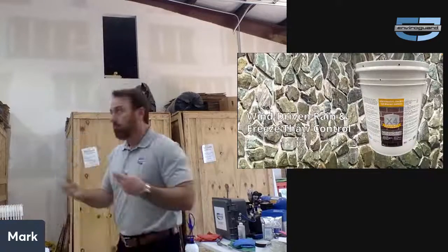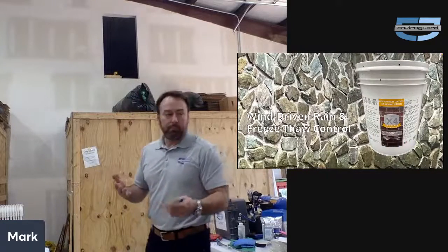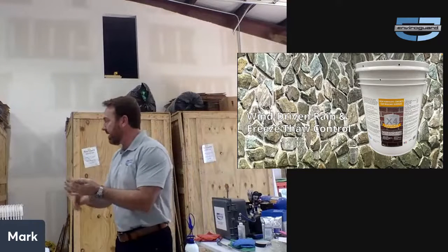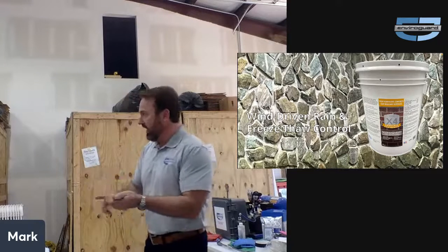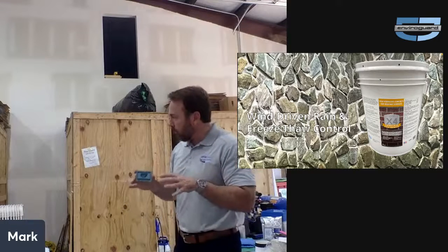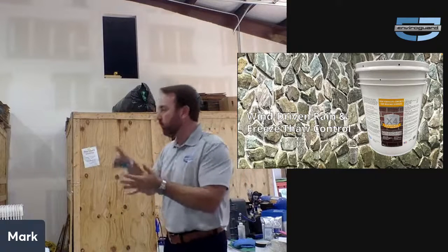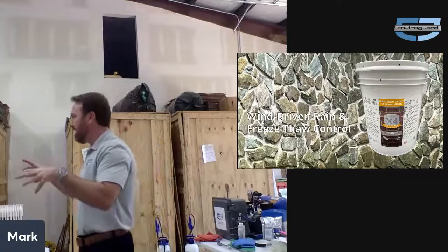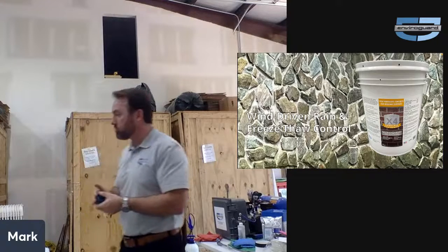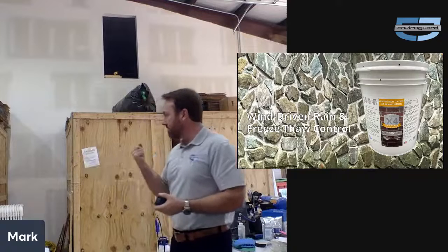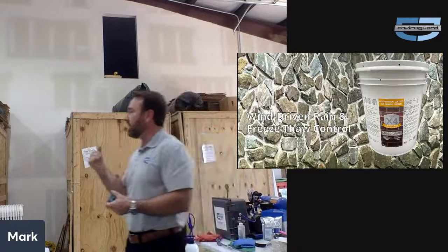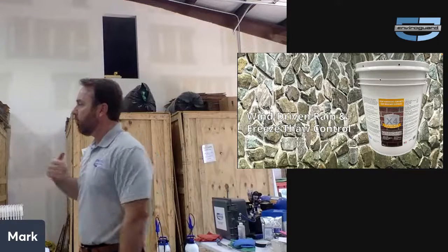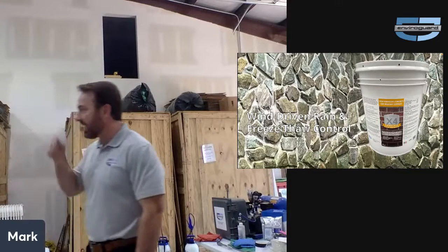Then, maybe conversely, but just as importantly, things like wind-driven rain, freeze-thaw damage in all exterior porous materials, especially brick and mortar, stone and mortar, EIFS, stucco, you name it, aggregate materials on commercial structures, suck up a lot of moisture, and it reduces the life expectancy of those surfaces, even just from repeated wind and rainstorms and things like that.